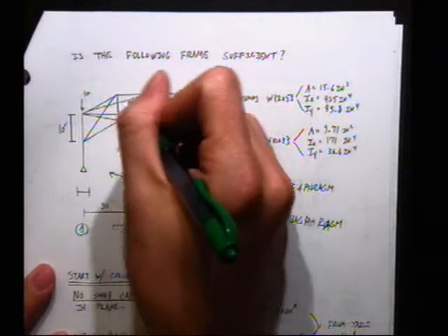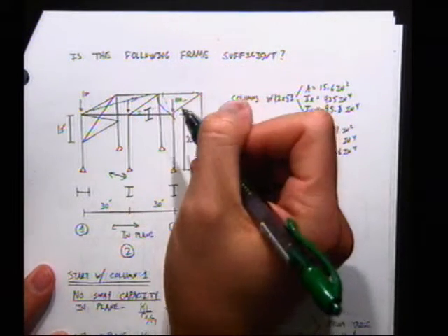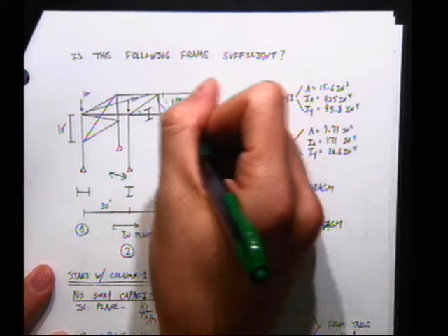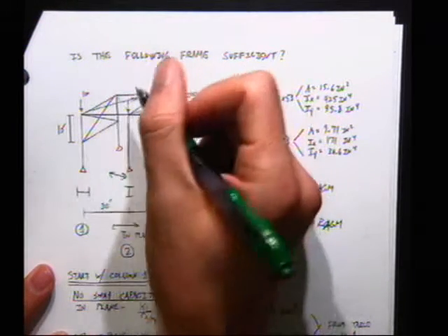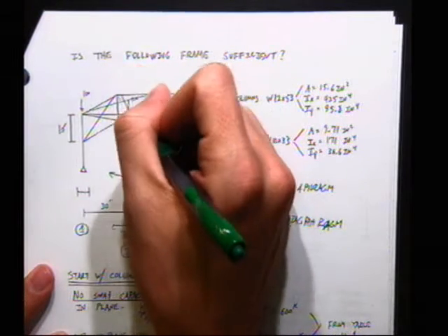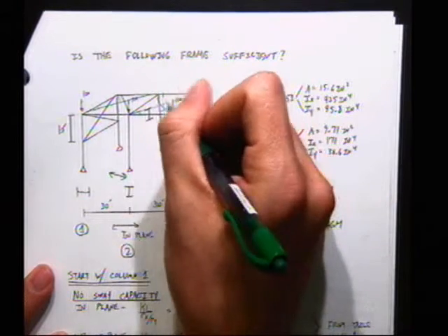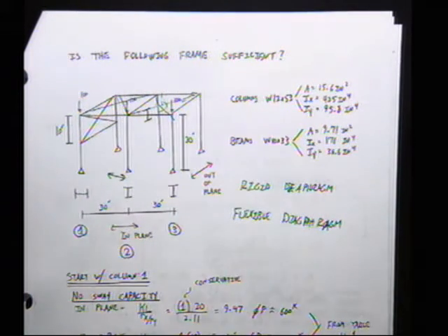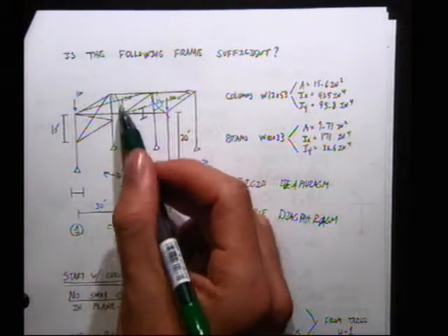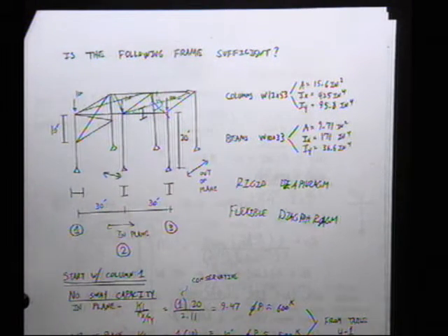The other thing I've seen that's really unfortunate is that they'll run a single cable from here to here, and they'll run another single cable from here to here, and say, oh, that's a good thing. Well, if something happens that causes both cables to break in this bay, there's going to be nothing that holds them in these bays because they're single cables. They're not different connections. They'll run a single cable through. That's a very common detail. It's a very poor detail.